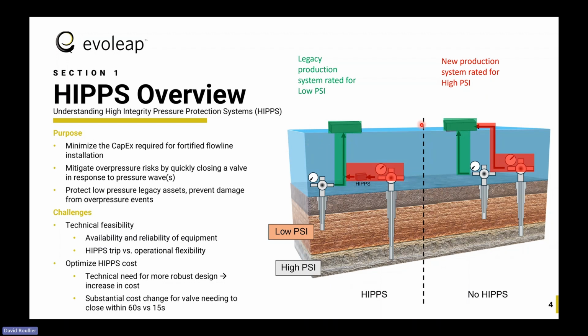So you have really two options to design this. One is, because the previous reserves had a much lower shut-in pressure, your legacy asset is not rated to take in new reserves that come from deeper formations or from abnormally high pressure formations, and therefore it needs some sort of pressure protection, or you would require a completely different set of risers and pipelines or subsurface facilities to bring that production topside while protecting your integrity, okay?